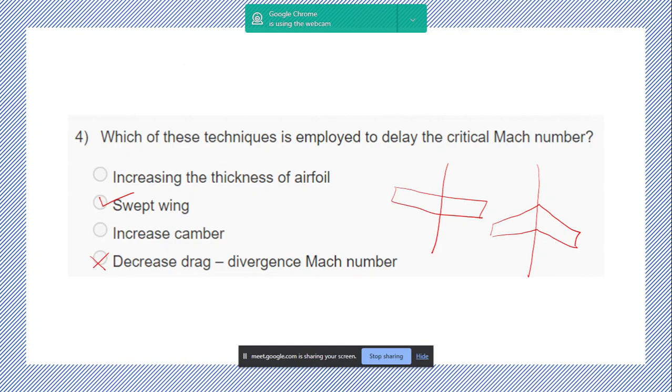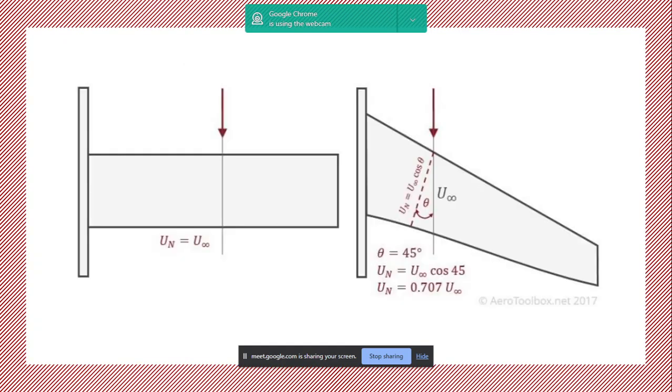Okay, so I think I have a figure that explains this. Your wing without sweep has the same velocity that all airfoils throughout the span of the wing encounter. So the normal velocity that each airfoil section of the wing encounters is the same throughout. So u here is just v. The normal component is always v infinity throughout the span of the wing; each airfoil section encounters the same normal velocity component.